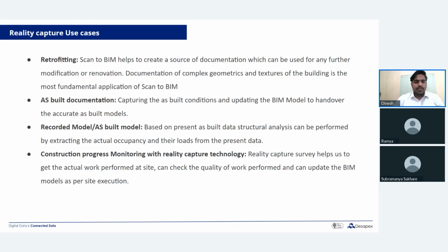And then record models. When you have certain assets, you generate the floor plans, you scan the above-ceiling services, and along with that, you can capture the number of rooms, furniture, and all the available live loads. This record of the entire model will be helpful for the owners to understand their loads, which can be used for structural analysis when they are renovating the project as well.